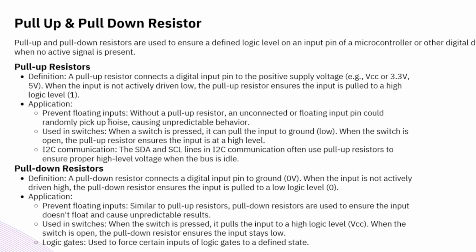Sometimes what happens if you leave pins floating is that they can show random behavior the moment there is any signal change. So whenever it is specified in the documentation or the spec sheet of that microcontroller or part to do a pull up or pull down, it's better you do it. If it is pull up, connect a resistor and provide 3.3 VCC or 5 volt to that. Without a pull-up resistor, an unconnected or floating input pin could randomly pick up noise, causing unpredictable behavior. It is also used in switches, and we'll be seeing this application.